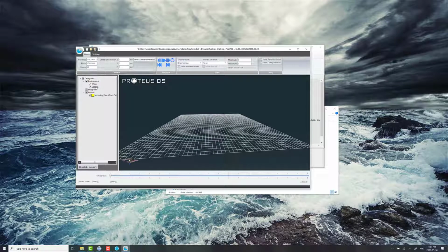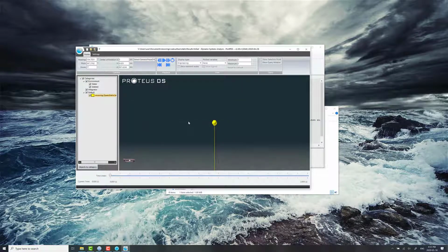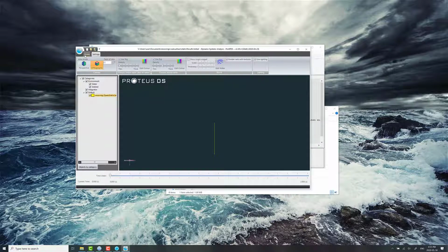So the other thing I like to do, you can find the mooring by double clicking on it here. But we still have this perspective projection. It's what it would look like if you were really there, and it looks like from your perspective what it would look like. So a better way of looking at what the mooring deflection looks like, if we go to settings and we click orthographic view here, we can get a nice side view of the entire mooring.